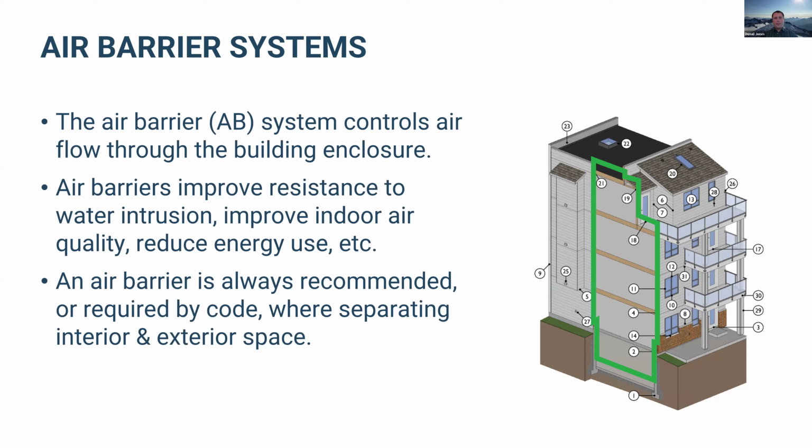They have to be continuous, and they can be put anywhere in the assembly. So there is often more than one airtight layer in the assembly. Quite often you'll see it as the WRB on the exterior sheathing, but sometimes they'll tape up the face of the insulation. That's the air barrier. Sometimes it'll be inside. It could be a vapor control layer that's sealed up as well on the interior side of the wall. Doesn't matter. It's not climate specific.